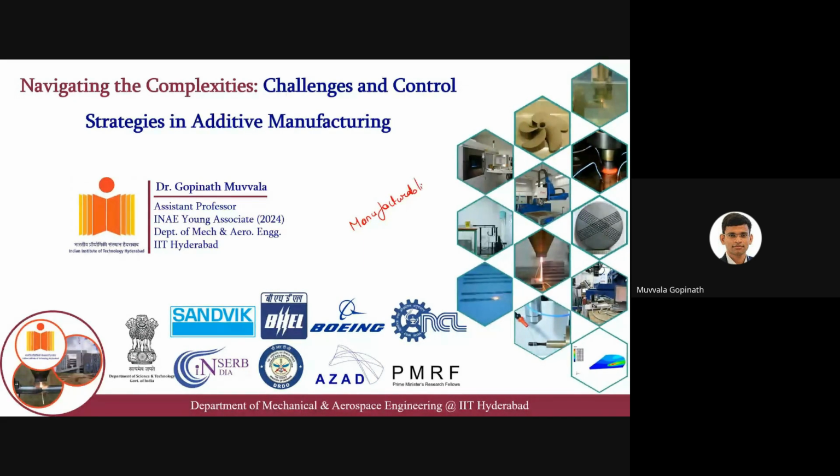So one thing in which additive manufacturing is a little bit advanced compared to other conventional manufacturing processes is manufacturability. Now, what do you mean by manufacturability? If you can see the component over here, which is a kind of impeller blade, that kind of impeller blade can be directly fabricated from a CAD model with slicing data and other aspects. But the more important thing is, if you want to do this in machining, it will take a lot of effort and what we call the buy to fly ratio.